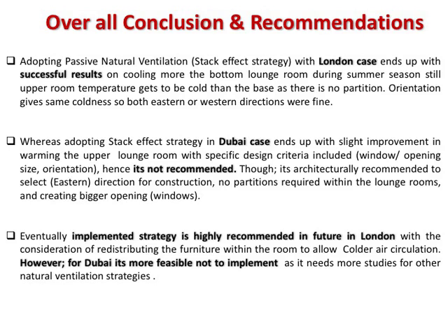Though it's architecturally recommended to select an eastern direction for construction, no partitions are required within the lounge rooms, and creating bigger window openings could help to at least keep the warm weather inside the lounge room if we are not going to adopt any stack effect strategy for the Dubai case. Eventually, implementing the strategy is highly recommended in the future in London, with the consideration of redistributing the furniture within the room to allow colder air circulation. However, for Dubai, it's more feasible not to implement it, as it needs more studies for other natural ventilation strategies.